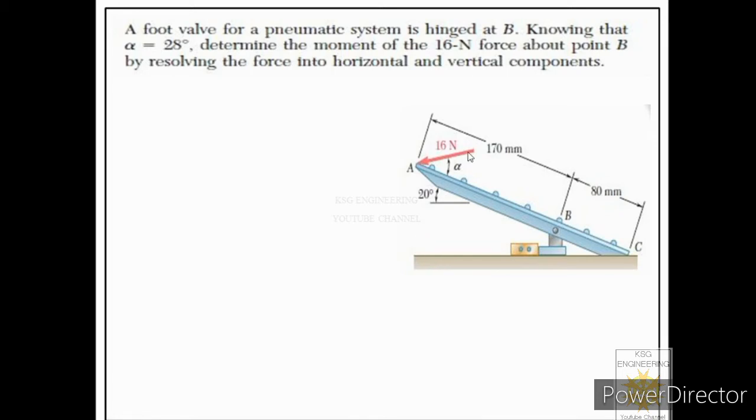It means we should first resolve this force into its components. Now how to resolve this force into its components? We have two choices. Either we can pick this point or we can pick this point in order to show its components. So let us pick this point. From this point we will draw one line along the lever and a second line perpendicular to the lever. But one very important point to understand is that when you have to resolve any force into its components, first of all we have to decide the axes. We have to decide the x-axis and the y-axis.